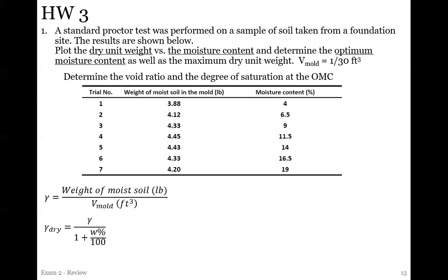I mean, you won't need to. You'll need to at least know the principles from that, but you won't need to memorize those equations or anything. So there's the other problem showing the SPT profile. The thing you need to know for that is that the SPT N value consists of the addition of those last two blow counts, right? Because in an SPT test, they hammer a drill bit into the ground 6 inches and count the number of blows it takes to go 6 inches.